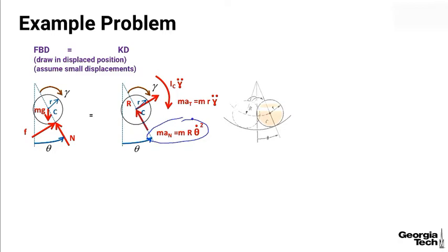Again, this goes back to my earlier course on dynamics, engineering systems in motion, 2D dynamics, where our normal acceleration is based on this angular velocity, theta dot, and the distance from the rotation of the center of the sphere, which in this case is big R. And finally, we have the I_C gamma double dot for the mass moment of inertia of the sphere times its angular acceleration.